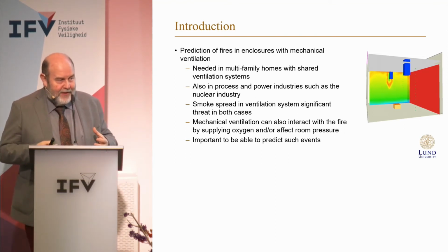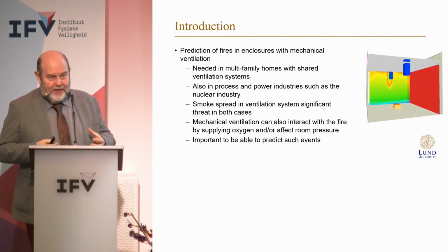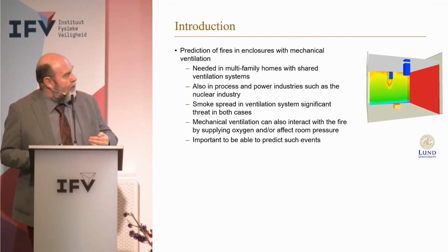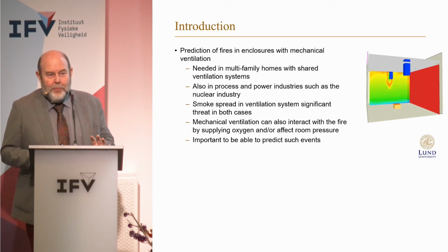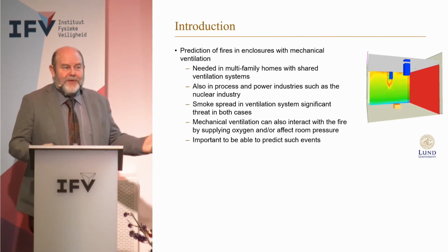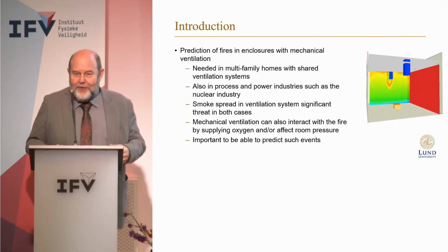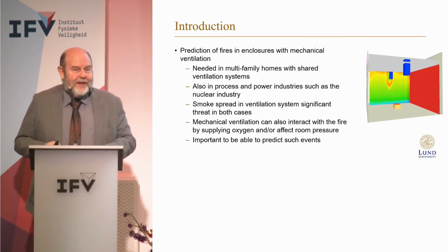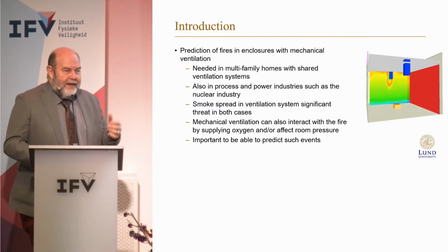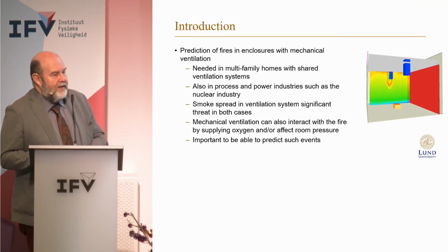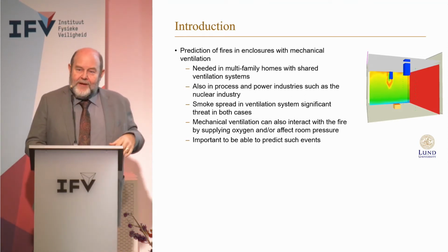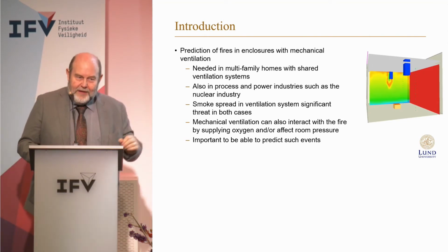And what can happen now is that this pressure becomes too big, so the air which comes into your room will be working against that kind of pressure, so that you will push even smoke through the inlet because the pressures get too high. And why do the pressures get high? It's because you have a tight room. There's no escape for the smoke apart from the exhaust, and the exhaust is mechanically steered. You cannot control it because it's the fans. And quite often the fans, as you don't want to go too much into the technical details, also depend on capacity and the temperature of the smoke and so on. So that happens. So the inlet somehow disappears. Flow can go down. It can even be smoke leakage.